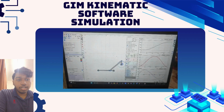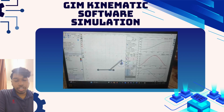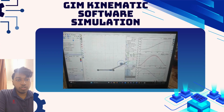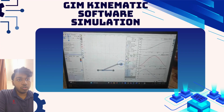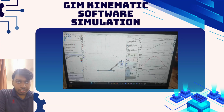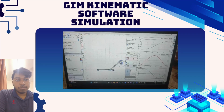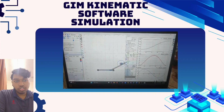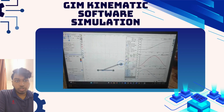You just have to select the actuators and place each coordinate at your preferred coordinates, and then you just connect the points and you will get this diagram. Once you get the diagram, you go to the results and click the play button, and you will see it rotating. But before that, there are some steps where you have to create the midpoint, and also a circle at the top so it rotates around that. So that's what you have to do for this.